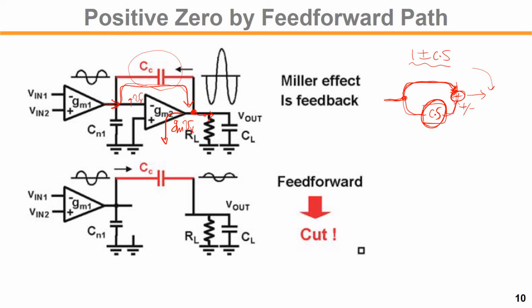So for the output voltage, the current going through the Cc: if the output approaches zero, you force that to zero, then the Vx over 1 over sCc current is exactly balanced, right? So subtractive, that is equal to Gm, let me say, minus Gm Vx equal to 0.